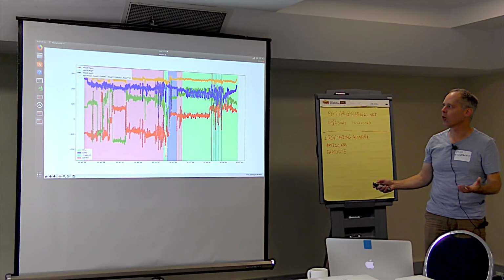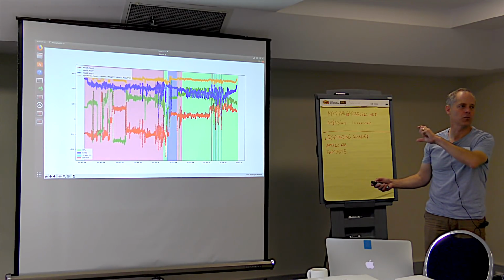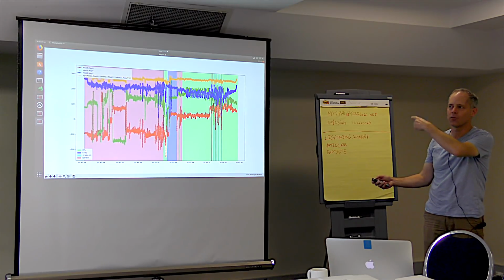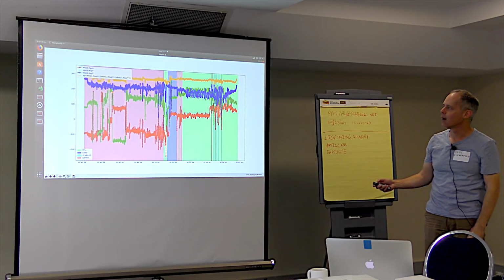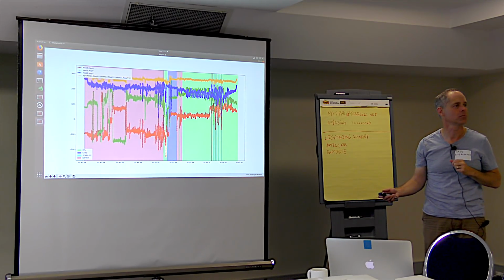So in this particular log, although it was tagged, initially the observation was, we think it might be an issue with the compass, and that was causing it. It was using the wrong compass, and because of the confusion with the compass use. In this case, as we saw before, the real cause of loss of navigation was the problem with the GPS.